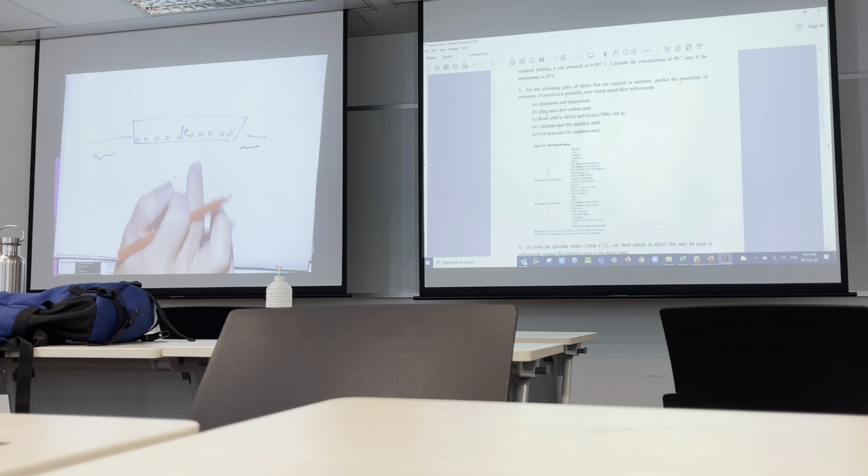Okay. The zinc blocks become the anode. Iron becomes the cathode. Then iron will not corrode, zinc will corrode. As long as zinc is there, I know the ship will still be okay. Oh, this one's the boat one. Yeah. So one day, if you leave it for too long and nobody goes and replaces it, then okay, now the iron corrodes.